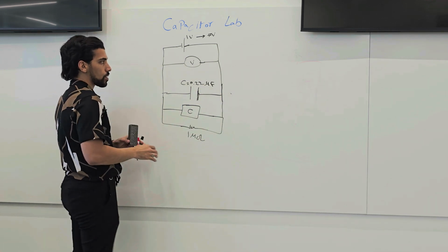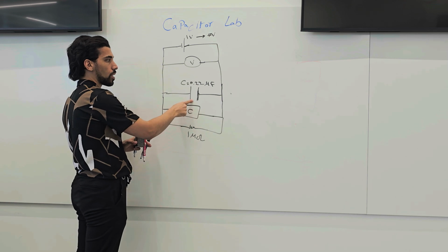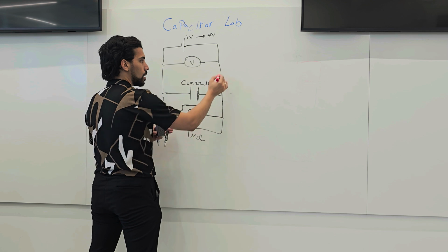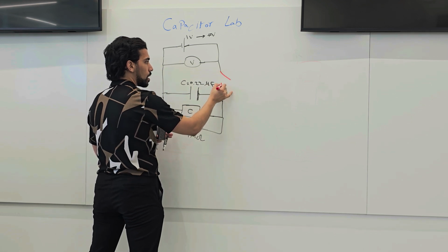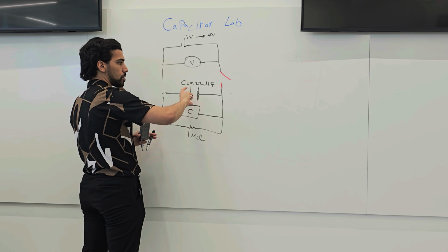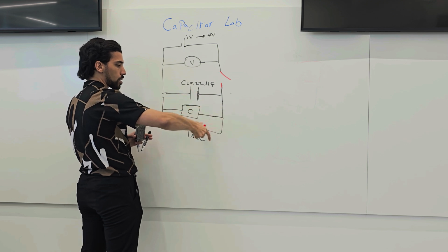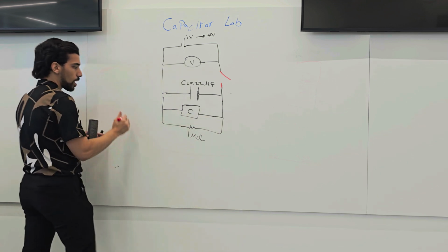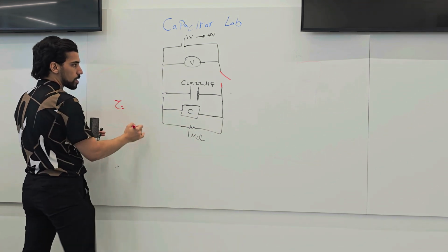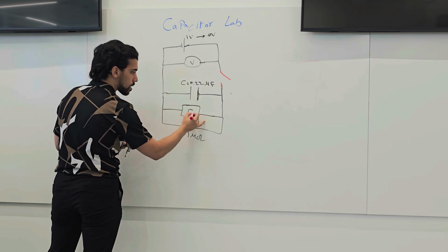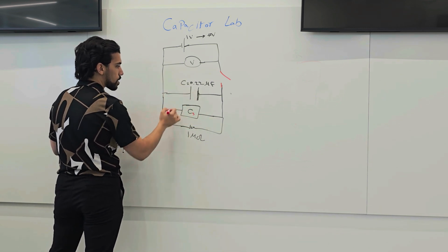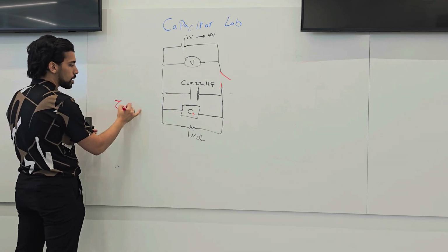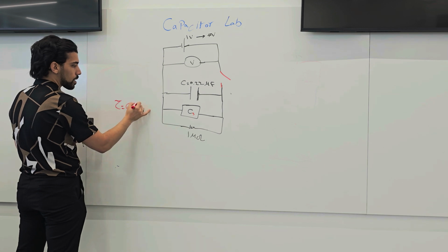So while the circuit is closed, we are charging. When the switch is opened, these two capacitors start to discharge inside the 1 mega ohm. And the tau in this case, let's say this is the charge sensor and this is a capacitor outside, so tau is equal to C total multiplied by the resistance.